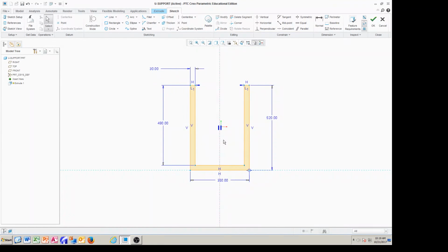and that's your dimensions for this. It looks like a U shape. That's the name of this solid model, U shape. So next, do not worry about all this fillet and round. We're going to add the round in a solid model, not in a sketching mode. In a sketch mode, when you try to place the fillet, it may cause a little bit of a problem with dimensioning, and you have to redimension. We're just going to leave it alone and continue.